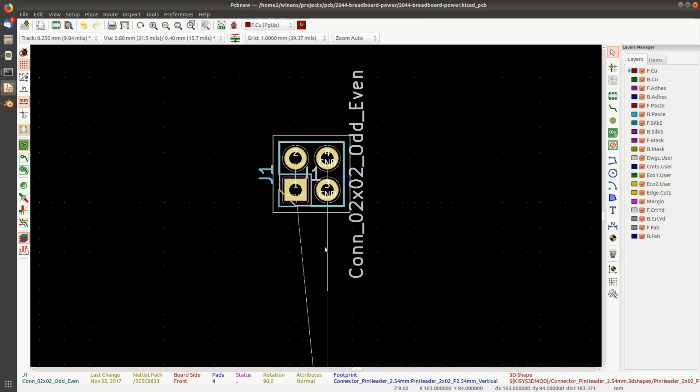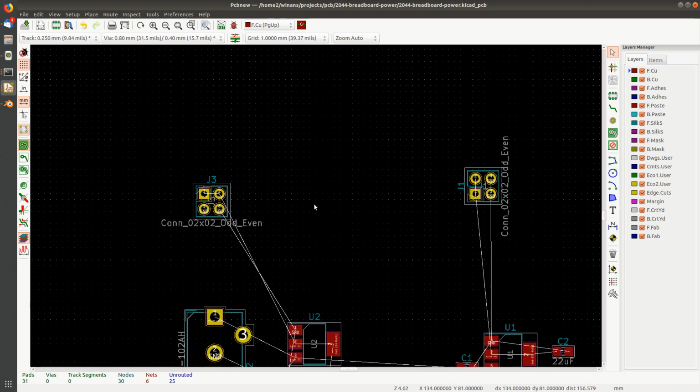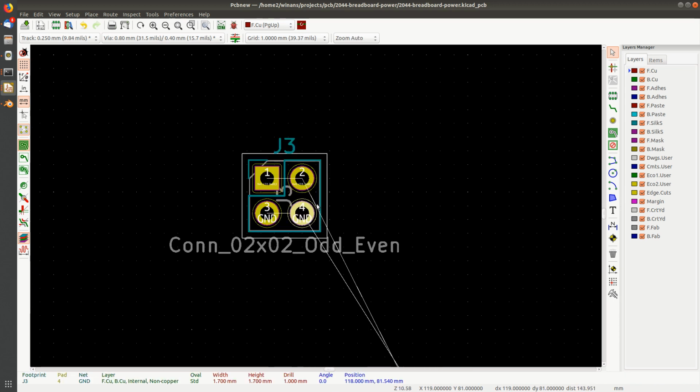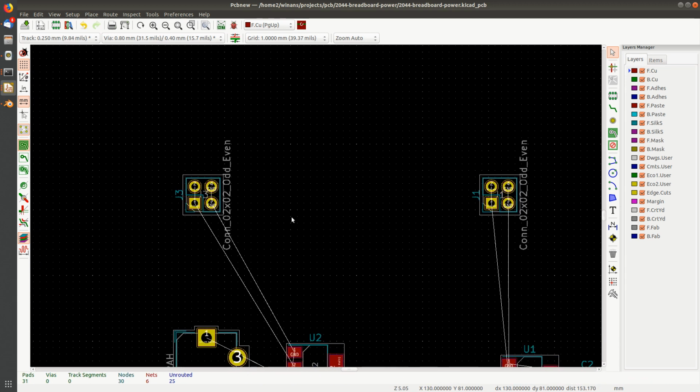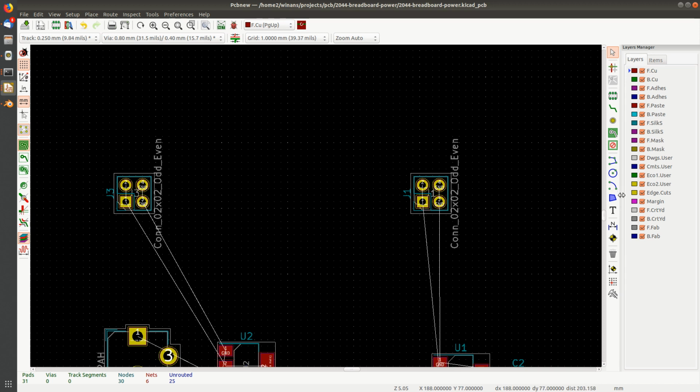Okay? I need to make sure that the two grounds run in line with the pins on the proto board. Same thing on the other guy. Select the whole thing, hit rotate until you have the grounds lined up. Now, my proto board has a red line and a blue line, and then all the other pins, and another red one and a blue one like this. So I want the grounds to sit in the blue lines, all right? So these are oriented correctly.